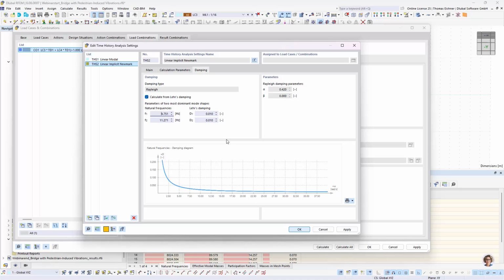So now let's talk about this damping approach for a minute, since I see a lot of confusion on it. This damping approach is something called mass and stiffness dependent damping. Mass dependent means the alpha value is a factor for the mass matrix, and the beta value is a factor for the stiffness matrix. In this way, the damping matrix can be described as a multiplication of those